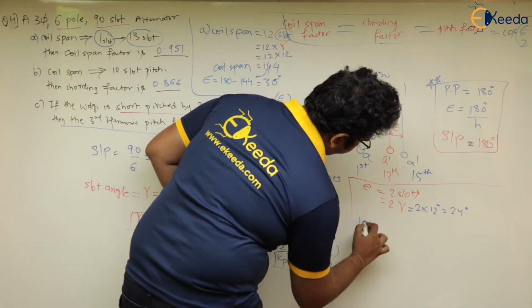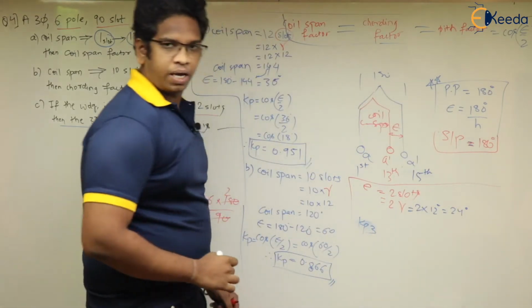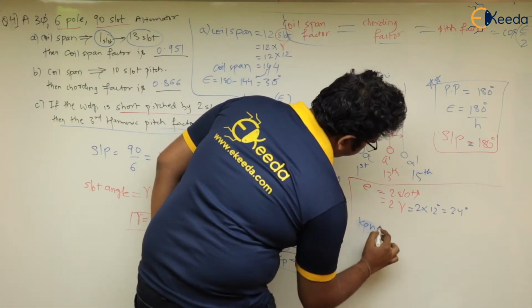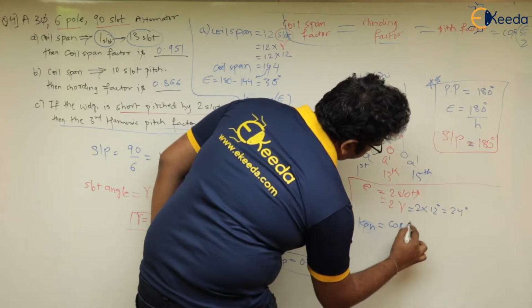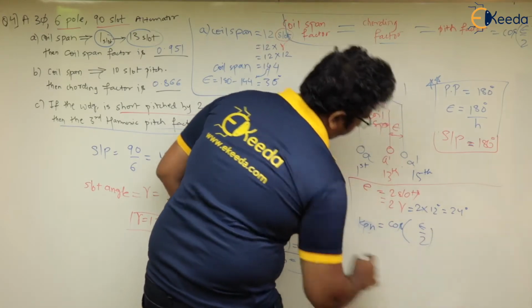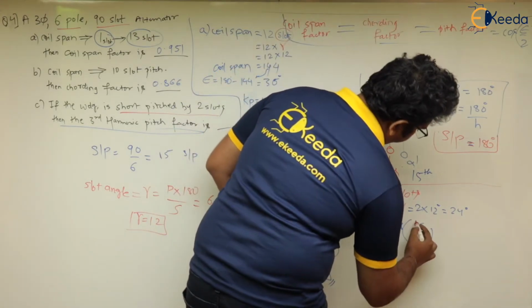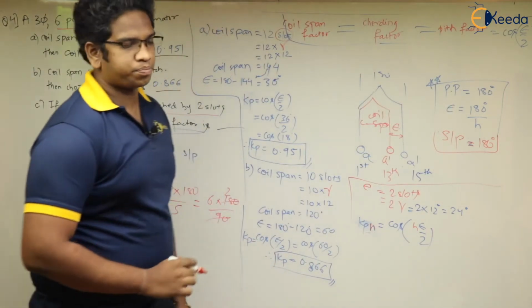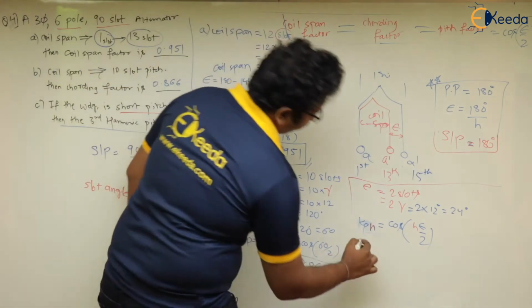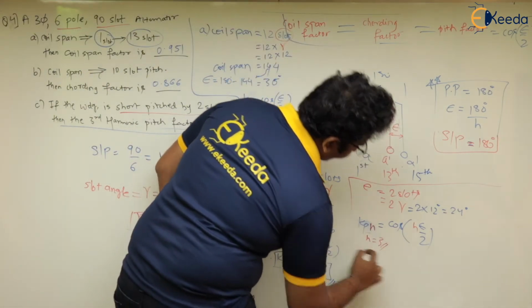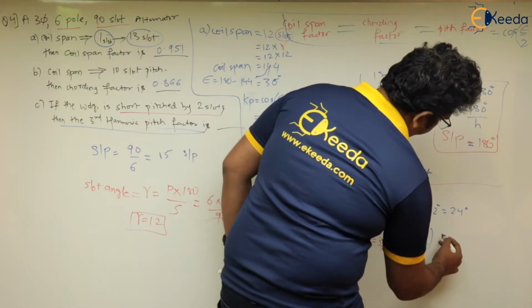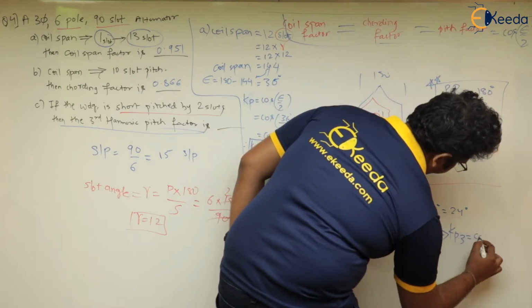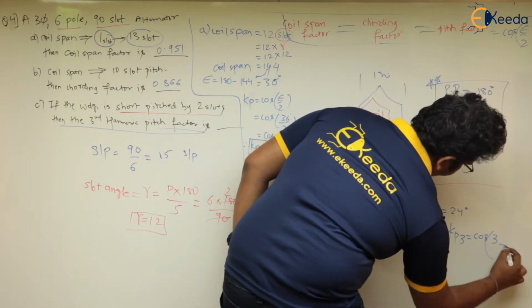If you think of Kp3, let us say Kph. Kph is going to be cos of epsilon by 2, but here epsilon is replaced by h epsilon, as we already know. So how much is h given here? h equal to 3. So Kp3 is equal to cos of 3 times epsilon by 2.